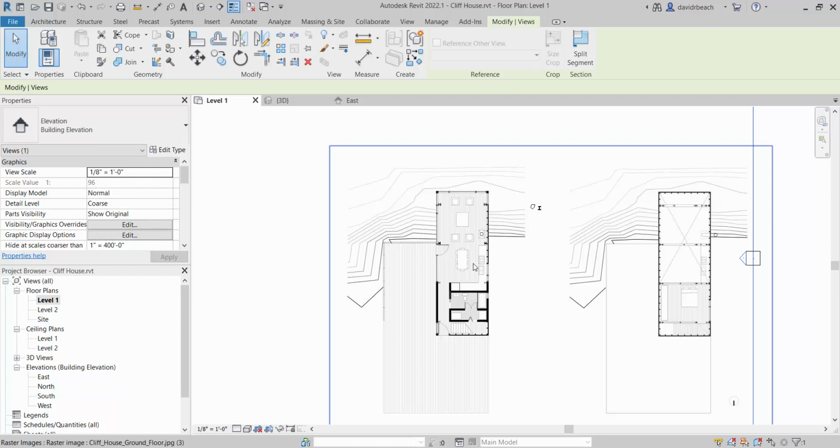So when I'm working in something like Form or SketchUp, those programs don't really care, right? You can just draw, it goes wherever. Hopefully it closes out, and hopefully you've done it right. But that's also why SketchUp and Form don't give you a super precise model all the time. That's why they can generate errors in terms of being watertight, in terms of coplanar faces, all of those issues that can pop up pretty easily. Revit's not going to let you do that. It forces you to model with a high level of precision. And defining, okay, this is where I'm going to draw it in 3D, is part of that precision.